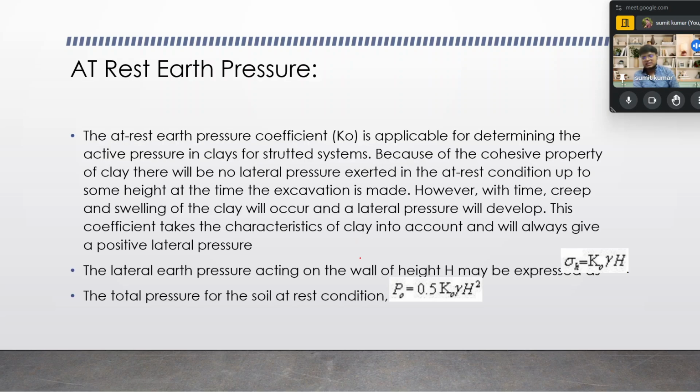Okay, now you see some more points over here. The at rest earth pressure coefficient mu by 1 minus mu is applicable for determining the active pressure in the clay for the strut system because of the cohesive property of the clay.